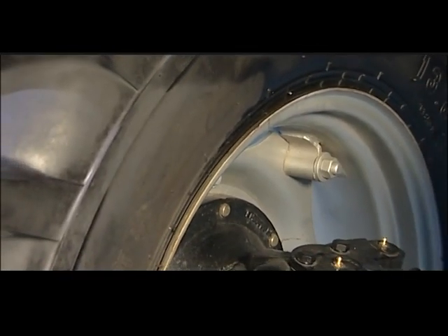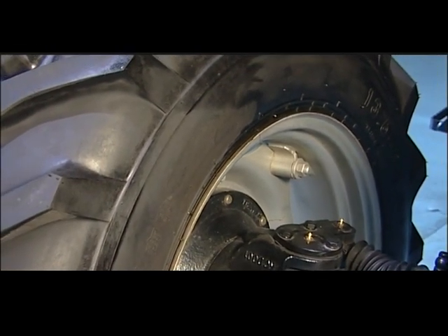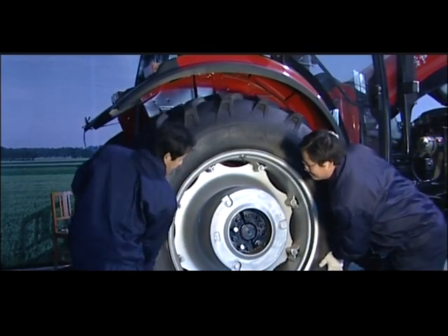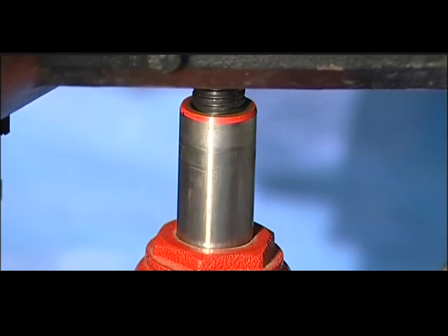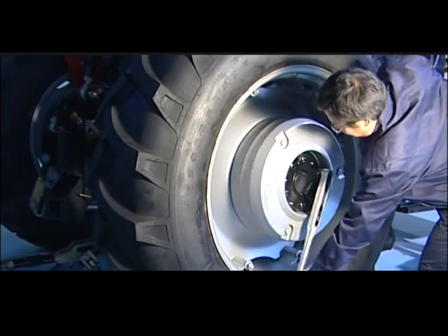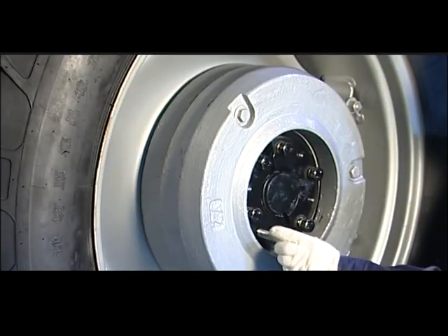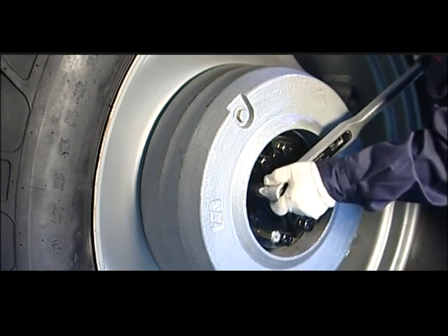Adjusting distance of front and rear wheels. Front and rear wheel distance is adjusted by changing the connecting position of spoke and hub. The sliding type rear wheel distance is infinitely adjusted by changing the hub position. The specific ways are: prop up the rear wheels with the hydraulic jack so that the rear wheel can rotate freely. Loosen the 6 fixed screws with a spanner. Do not remove the screws. Use a suitable length of M16 bolt to screw into the bushing. Pull out the bushing from the rim.